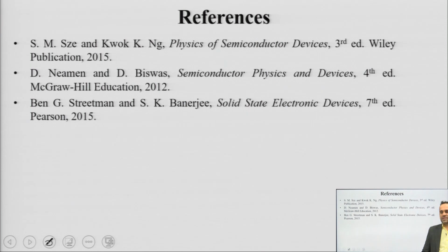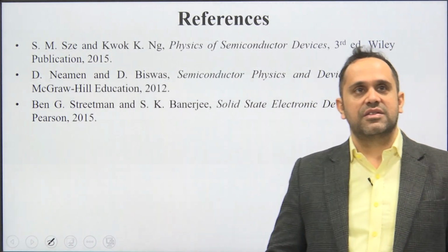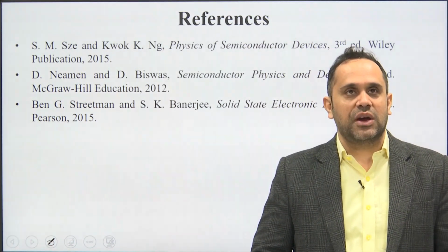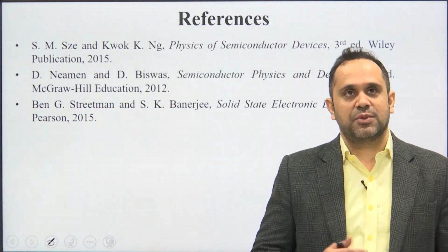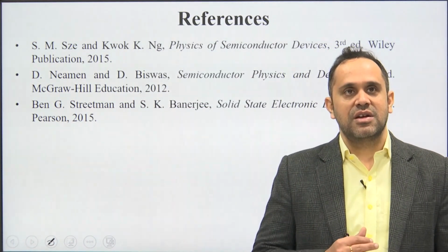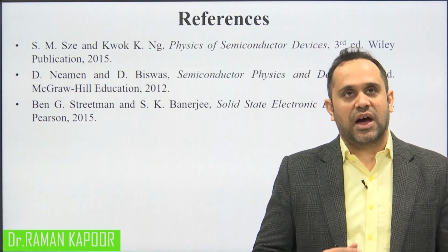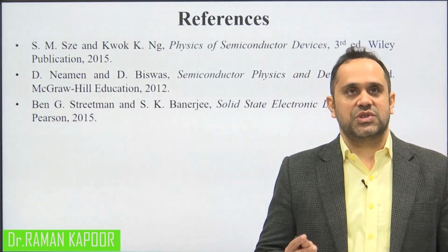Okay. So, these are some of the references you can refer to for the content covered in this lecture. We have covered a very important topic known as Shockley equation and diode capacitances. In forward bias, you get exponential current, in reverse bias, you get 0 to constant reverse saturation current. This is why a diode is unidirectional, it works like a switch.